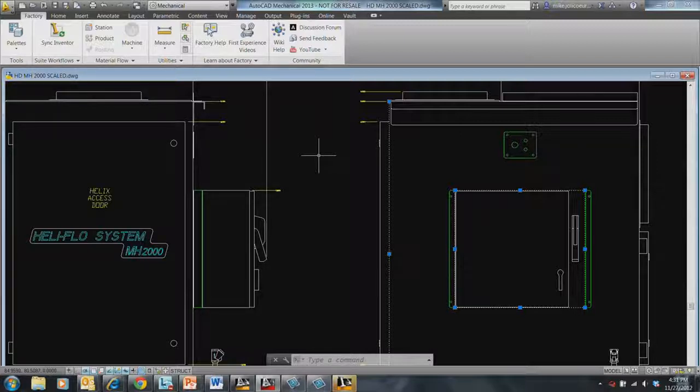Well, you can. The question is, you notice I just have a very simple thing right there. It's just changing the width and the length. Can I do more than that? The answer is yes, absolutely. By using iLogic, I could basically say I've got configuration A, configuration B, configuration C. So I'd go and pick those, and it'll change everything about them that needs to be. And depending on if I leave some of the dimensions open on those too, I can also change sizes.